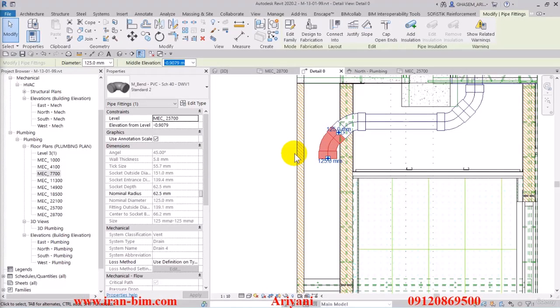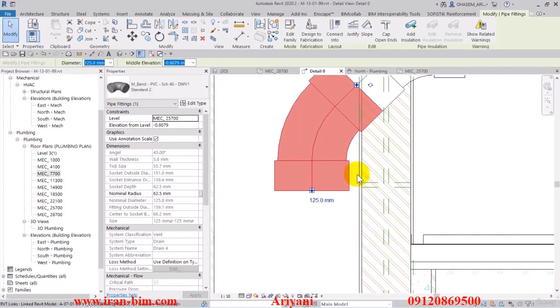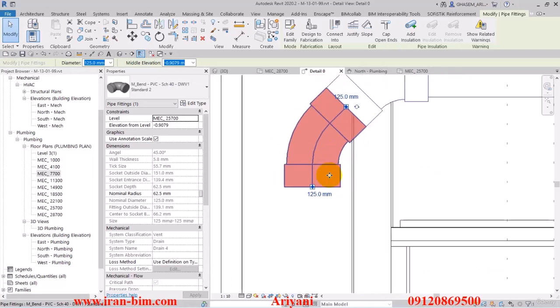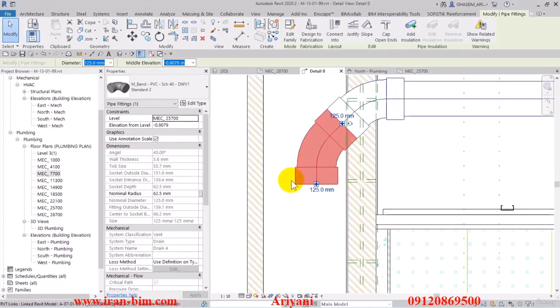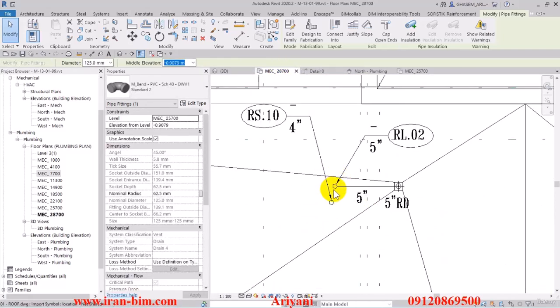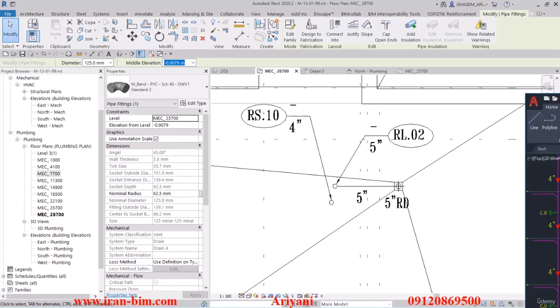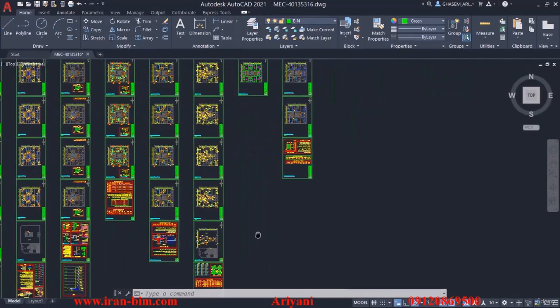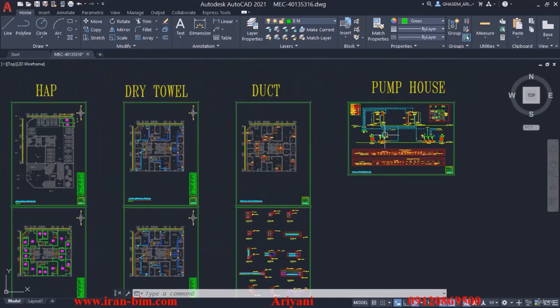So remember, when you're modeling structures like these, you have to pay careful attention to details like these. As an example, in here, I can move the fitting closer to the wall, but does the system behind it fit as well? Is the question, because the U support needs a couple of centimeters for space. Even if you're not going to fit the U support, you need to leave the space empty. And where you're drawing the plan, you need to make sure, is this area enough for about 10 of these supports or not?